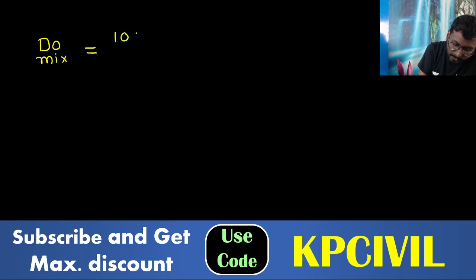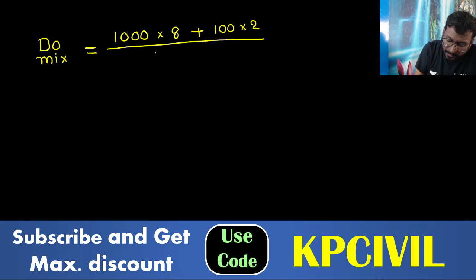First 1000 MLD with DO 8, next 100 MLD with DO 2, divided by total discharge, 1000 plus 100. What are you getting for DO mix now? Weighted average DO mix you are getting 7.45 mg per liter.